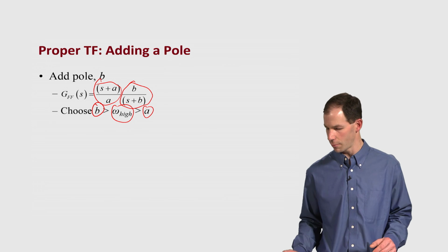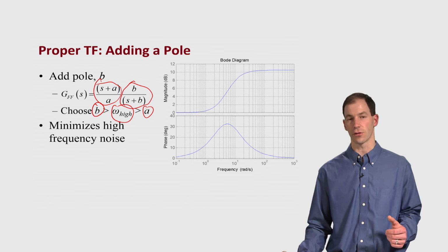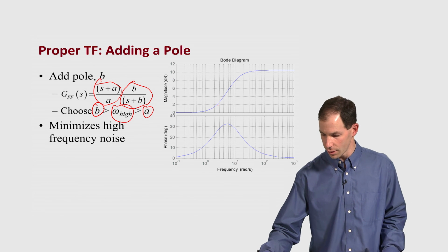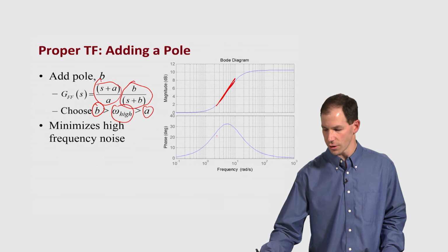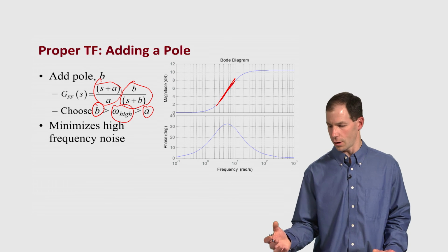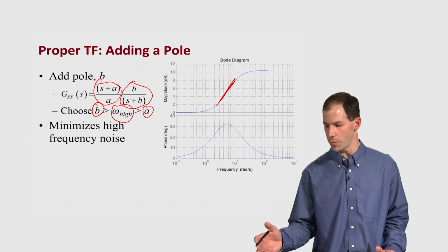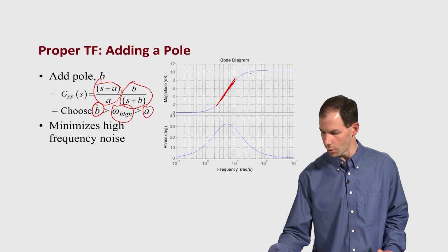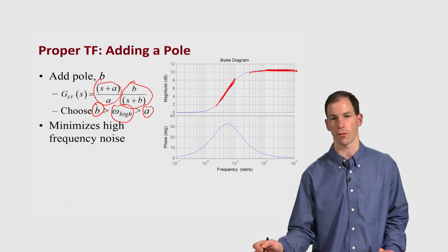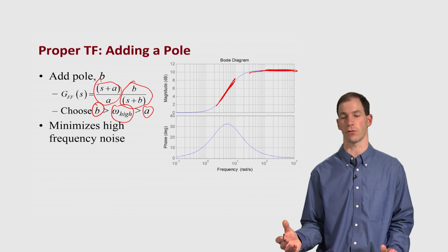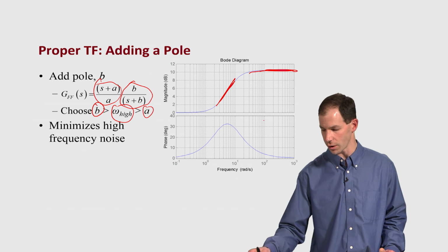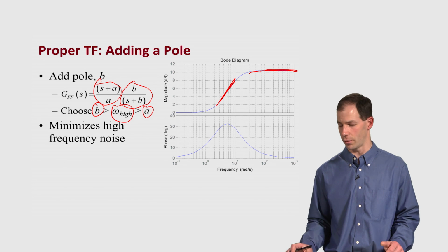So this is now my feed-forward system, and you can see from the Bode plot, I get the increasing magnitude that I want, or the gain that I'm applying through that mid-range of frequencies, but then I'm rolling this off and flattening it out at higher frequencies so I don't amplify that high frequency noise. And similarly, I'm getting this phase angle plot that I want.